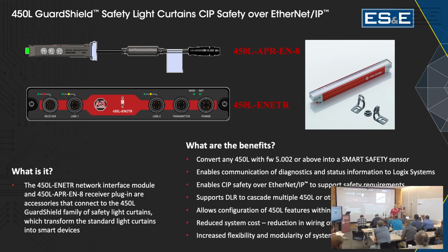Most of the I/O blocks and adapters have an Ethernet in and an Ethernet out. That means they can support linear topology, if I just want to daisy chain, and they also support DLR, device level ring. Device level ring is fault tolerant in that I can lose a segment of the ring and still continue to function. With the GuardLink, we've also got power in and power out. Notice also, and this is the star of the show too, because it's what's talking to this, that is the IO-Link Master, the brand new one.